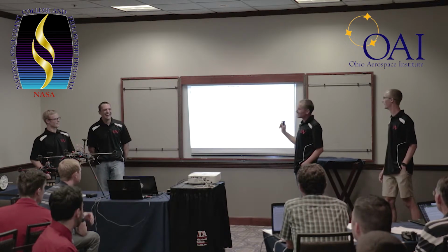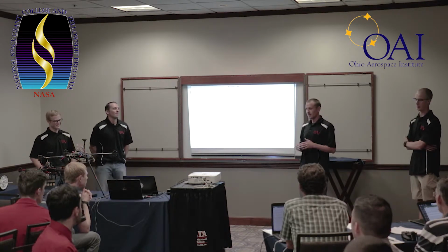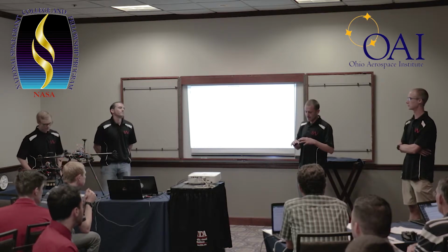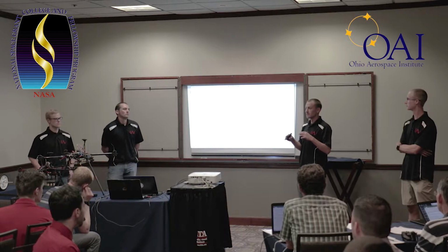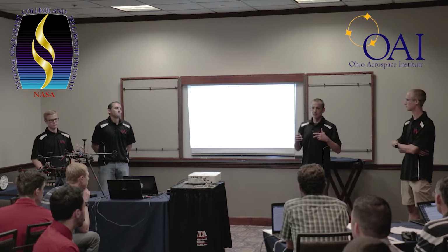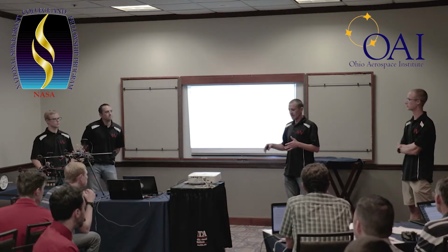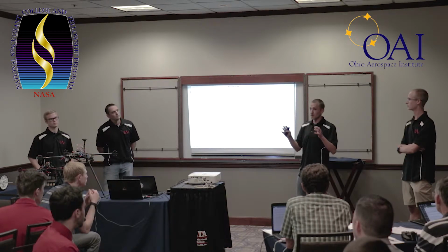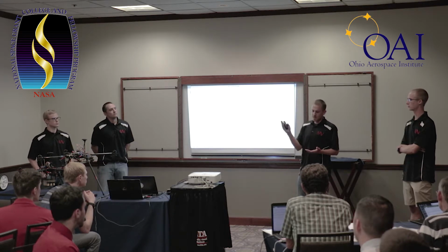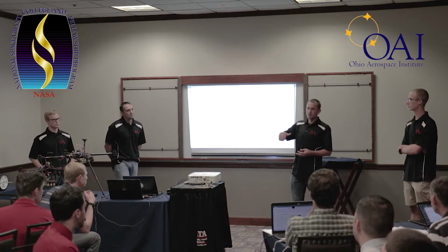All right, so FlyMaster is a software system that I developed. It's based on ROS, and it communicates with MAVROS 2 and PX4, in order to create this easy system for everybody in the lab to use to actually take UAV flight in the air. So there's always a bunch of people working on algorithms for obstacle avoidance or a bunch of stuff. So this software was a means to reduce all this controls burden that everybody has when they try to fly these things. So it defines an easy interface that doesn't rely on the actively changing interfaces of all this open source software system.